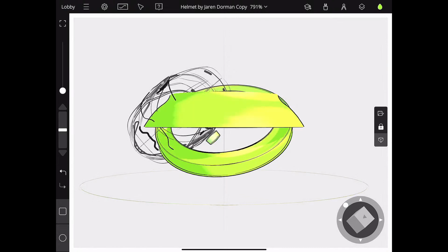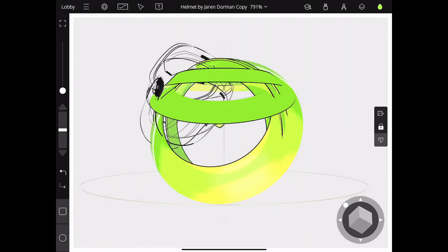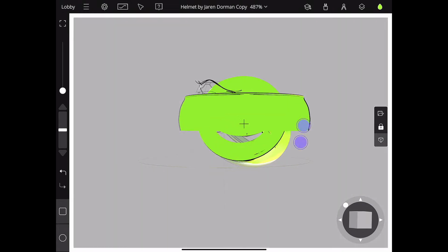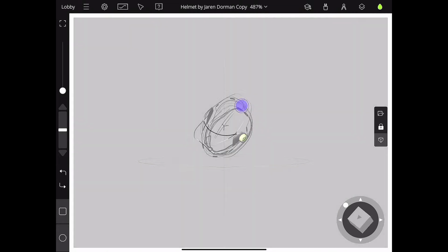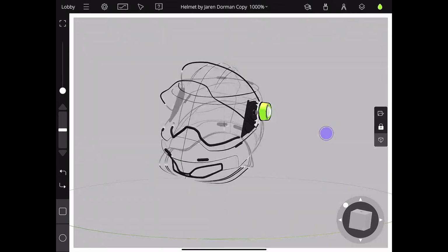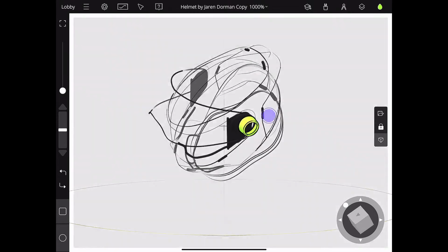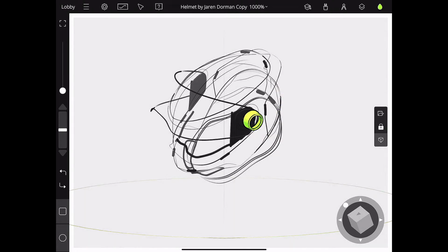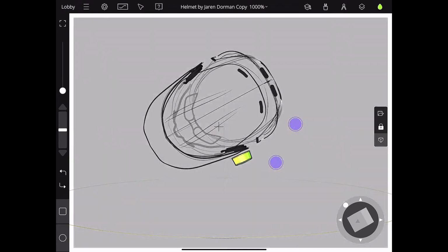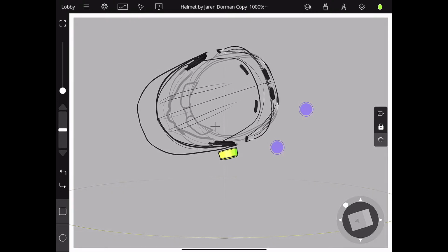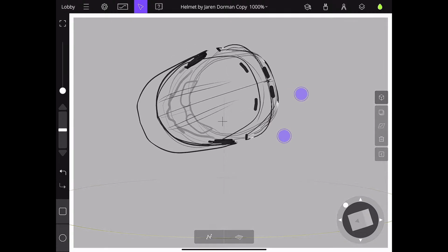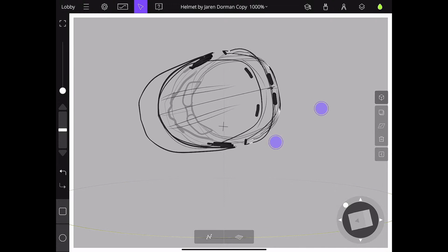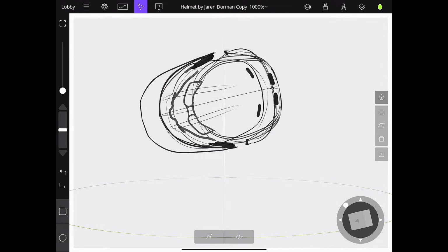So if we move, we can continue to draw some more revolve shapes. You can see they're all on different planes, because wherever we're facing is the draw plane. So that's how you can get that revolve at an angle, by getting that camera view and then just aligning it to the axis that you want to draw on. So I'm going to try and delete this one. Align it just a little bit. Here we go. Oops.